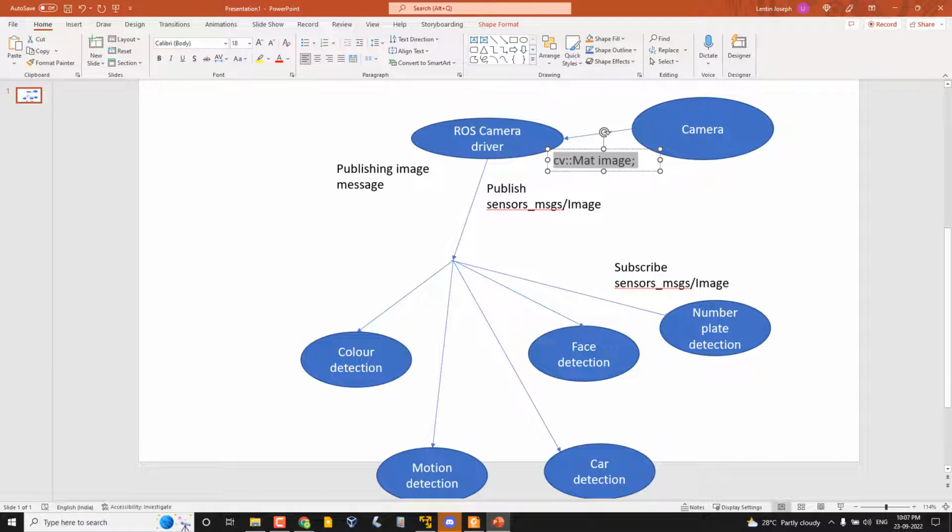There is a question from Rohan: what is the difference between an RGBD camera and a stereo depth camera? The RGBD camera is what the Kinect or RealSense is. It has an RGB camera with depth; commonly we call RGBD the depth camera.